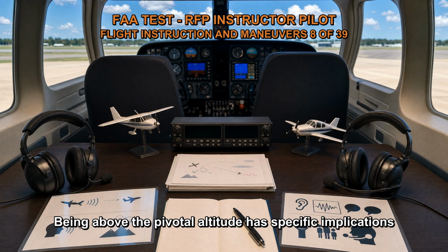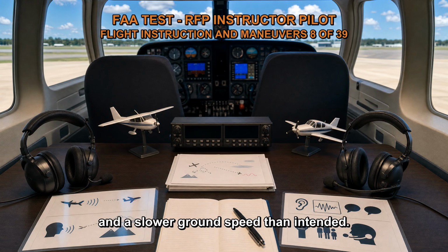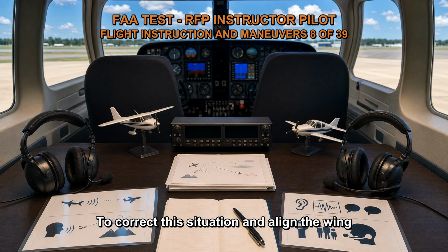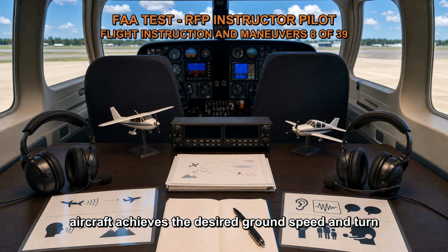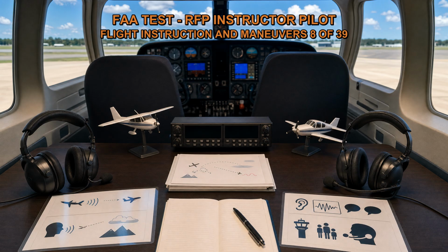Being above the pivotal altitude has specific implications for the maneuver. It typically results in a larger turn radius and a slower ground speed than intended. The decreased ground speed leads to the wing appearing behind the pylon from the pilot's perspective. To correct this situation and align the wing properly with the pylon, the pilot needs to ascend to the pivotal altitude. Ascending to the pivotal altitude ensures that the aircraft achieves the desired ground speed and turn radius for a properly coordinated Eights-on-Pylons maneuver.